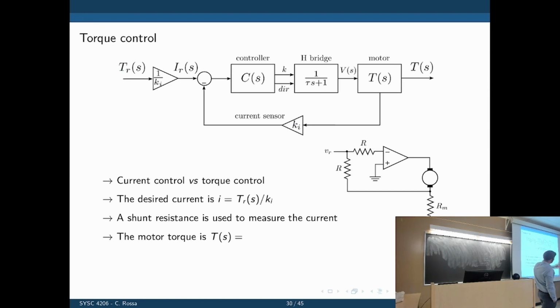By measuring the voltage across that resistance, what's the current? If we measure a voltage V here, what's I? It's V over R, right? That's as simple as it is. So when you buy a current sensor, there are different ways, but most of the time it's just a resistance in series with the motor main winding, and we call the resistor itself a shunt resistor. Right?